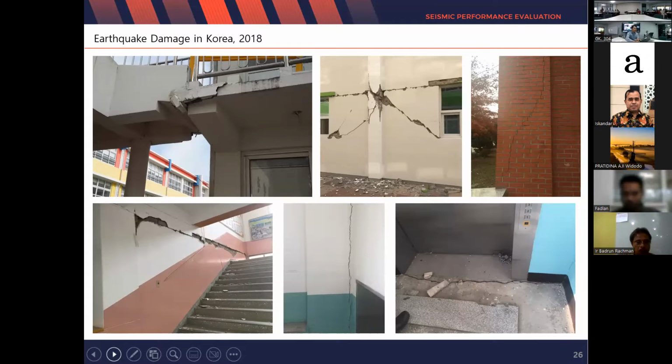You can check the most critical cracks in the picture. A joint crack and a column masonry crack are shown in those pictures. Especially a diagonal crack or shear failure of a column is really important because it can cause building collapse.